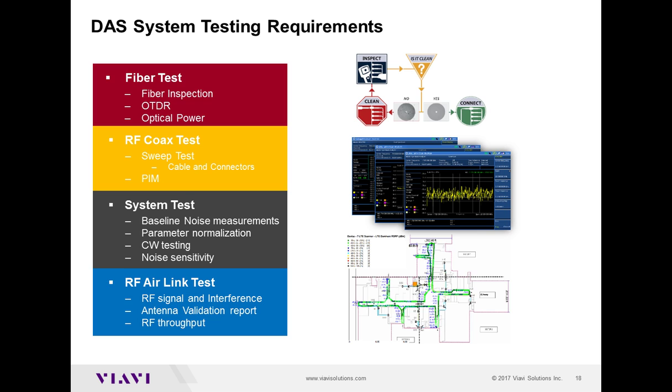And of course, for the coax aspect of it, if you're using jumpers and things like that, ensure your jumpers are good quality and everything is done right, and you basically have the calibration kit and everything, so you can validate that. And then you can run sweep tests on cables, and of course if there are PIM issues, you can validate using either a PIM tester or basically detecting PIM using spectrum analyzers. There are some spectrum analyzers that can support that, what have you.